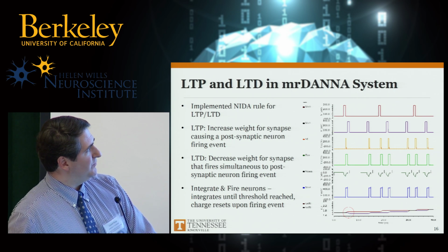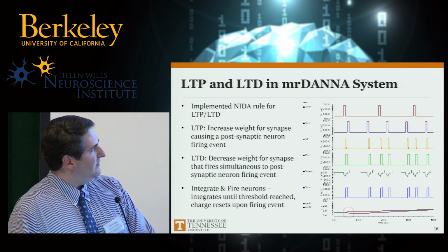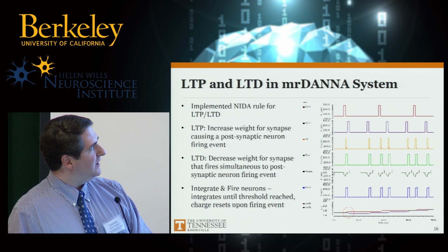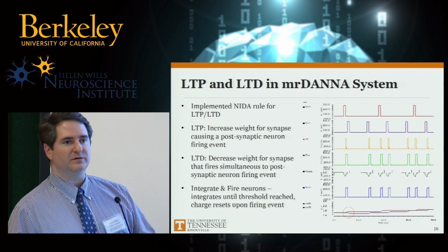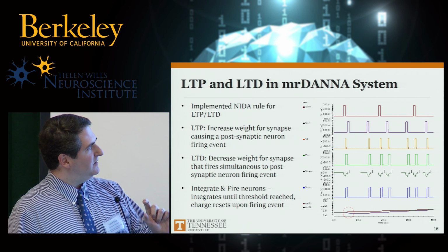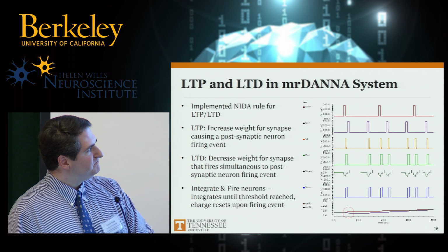It might be kind of hard to read. I should have had a schematic to go with it. We'll assume we have two synapses driving a simple neuron. These would be the inputs. So we see a train of very simple little pulses. Those are our spikes. I should note we're just representing these as essentially half VDD, so it's going up to 450 millivolts in this case.